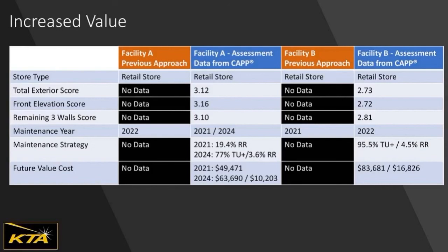By conducting a condition assessment, if we can see the comparison here, if we're strictly doing it by a last touch date, we're basically just adding whatever the schedule is, 4, 5, or 6 years to our last touch date. But if we're doing a condition assessment, we're able to know the condition score. We're able to prioritize. We're able to determine the optimal maintenance year, which may or may not always be on that 5 or 6 or 7 year cycle. It could vary based on environmental conditions.